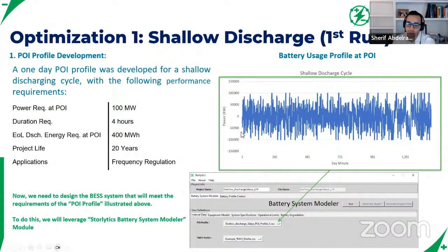In this case, this is a frequency regulation market signal. I think it was from PJM, though I may be mistaken on that. It has exactly the same number of equivalent cycles per day as the first case. So when you look at the two, it's 1 cycle a day here and 1 cycle a day here. The only difference is the first case has deep discharges, and the second case has more shallow discharges, which you would expect from a frequency regulation use case or ancillary service.